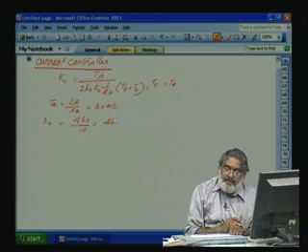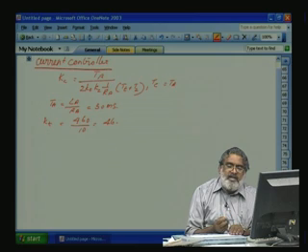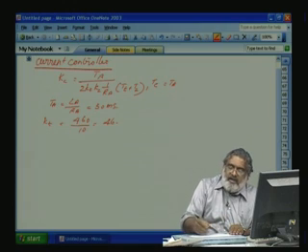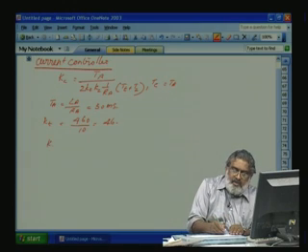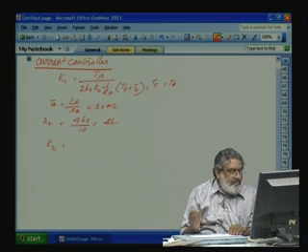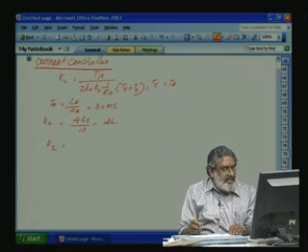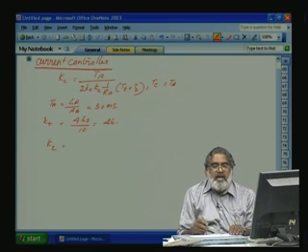Now, for the speed controller output, the previous rating said the maximum rated current can go up to 1200 amperes. Here also, for the current feedback filter gain K2, the moment 1200 amperes current comes, we should get a feedback voltage of 10.